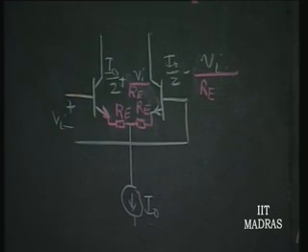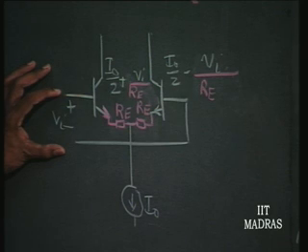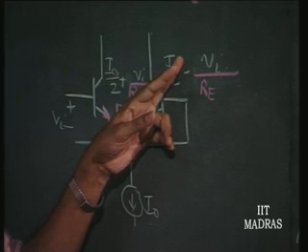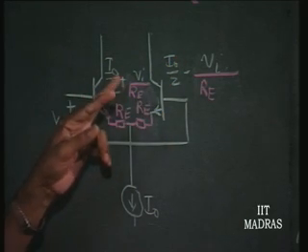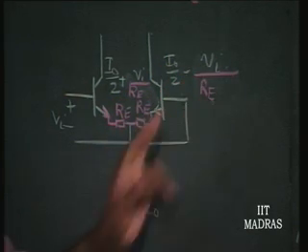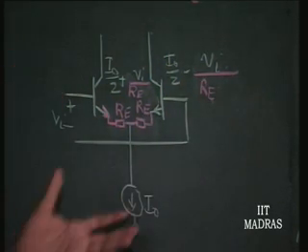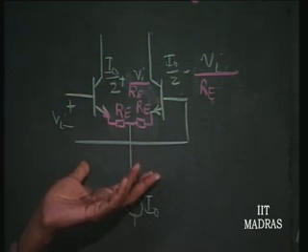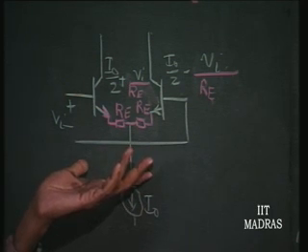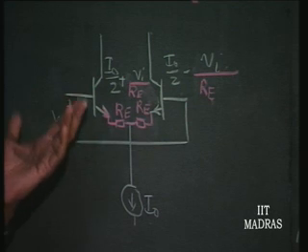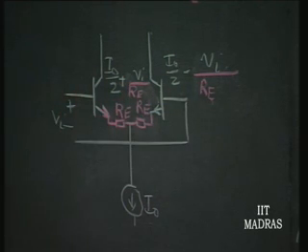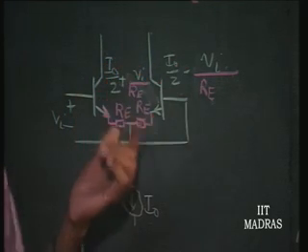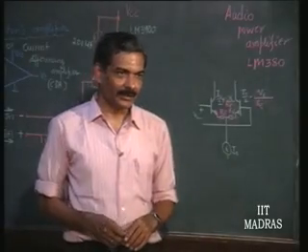So, we are able to produce from a differential input voltage a differential current output with a common mode current equal to I naught. See, I naught by 2 plus V I by R E, I naught by 2 minus V I by R E. So, this is nothing but a transconductor stage, you can say, whose conductance value is going to be pretty stable and is going to be equal to 1 over R E. So, you can say this is a transconductor amplifier, right? Differential input voltage and differential output current. This is obtained by feedback here.